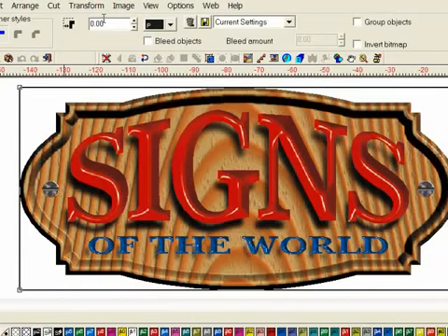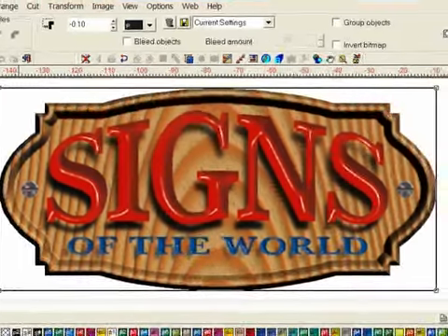For this example, I need the contour line to cut right on the edge of the print, so I will set the offset to a very slight negative value, and this should eliminate any white edges from appearing on the outside of my sticker. I also want to use point as my corner setting to keep the corners nice and sharp. Okay, with my settings made I can now click apply.